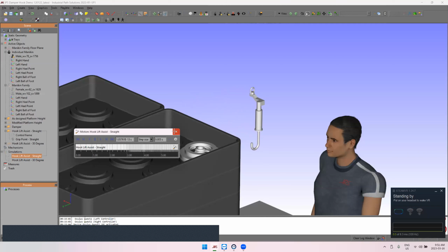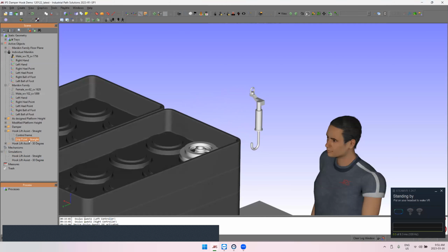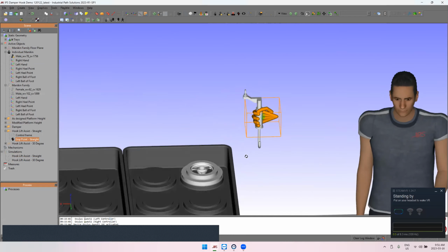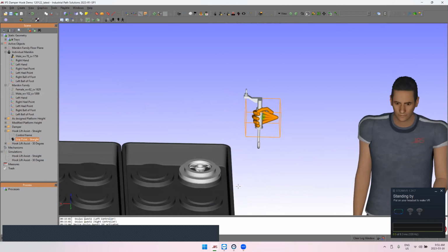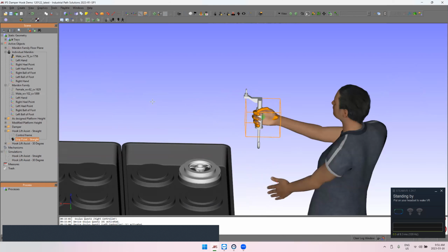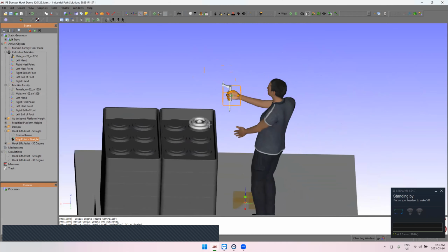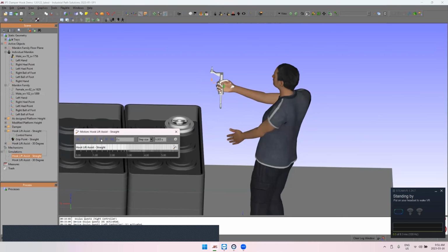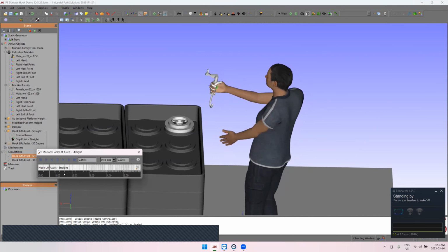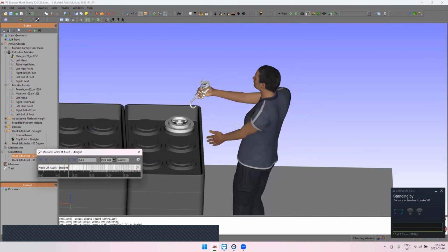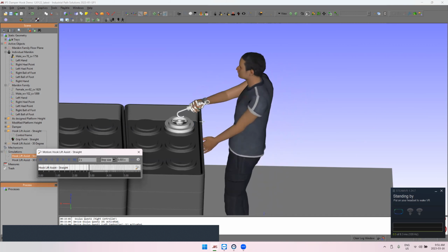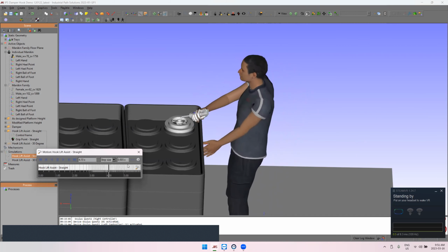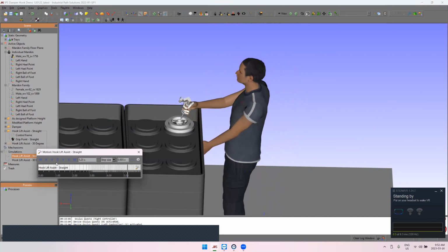However, if we did have a hand placed on that lift assist, there may be issues with hand clearance. So utilizing what's called grip points within IPS, we can turn that on. We can have the mannequin or the hand attached to the end effector, and if I bring this onto my mannequin here, he will assume the posture and that grip. When I play through that motion again, this mannequin will actually follow that path. Using the software, it will attempt to hold on to that lift assist to the best of its capabilities and move through the motion.